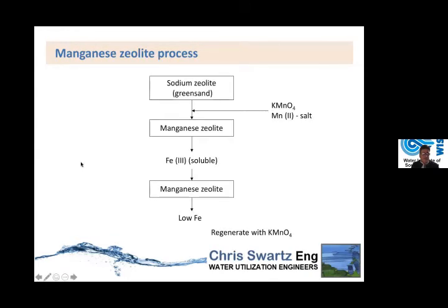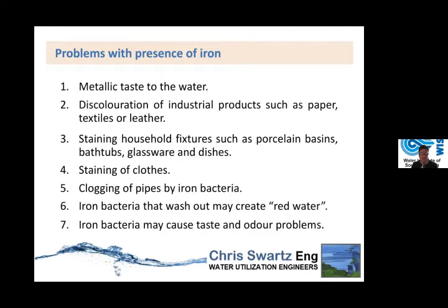What they often use is sand, called green sand, where you get a manganese dioxide coating forming on the sand. You can do that with potassium permanganate, for instance, and then that enhances your iron removal, and you can use such a green sand filter effectively for that.